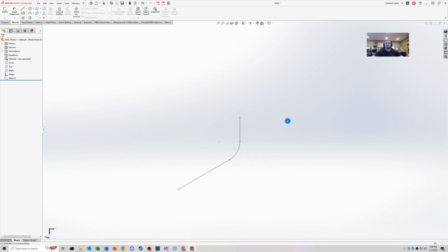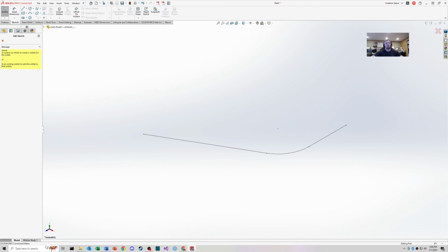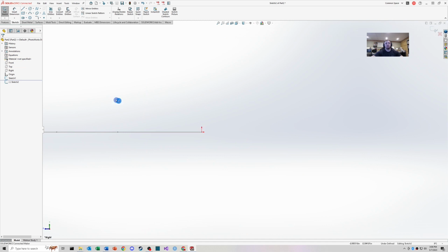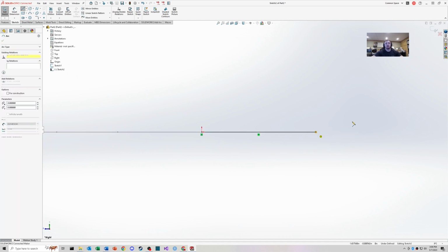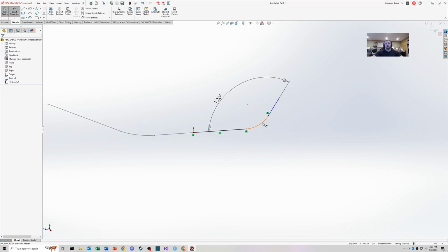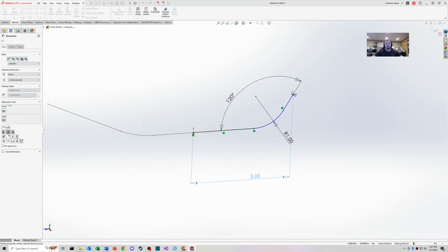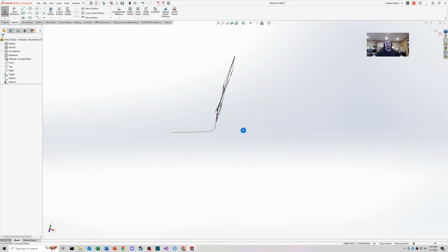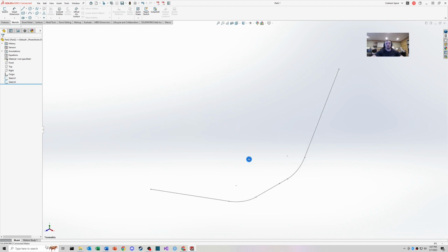So I have a sketch here, and let's say I run into a scenario where I have two sketches that are merging here at the same intersection. If I have another sketch like this, let's make this another 120-degree angle and define this at a 1-inch radius. Then from there to there is 3 inches, and from here to here is 3.5 inches. So I have two sketches that intersect, right? But sweeps don't recognize that these two sketches are going to intersect by default.